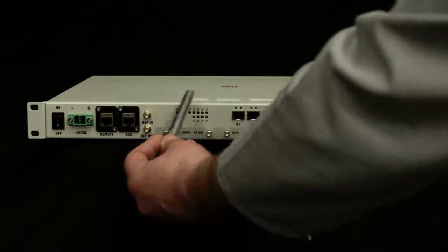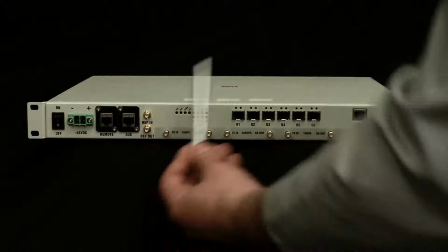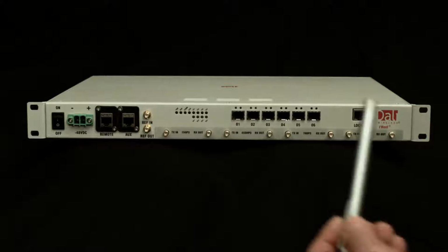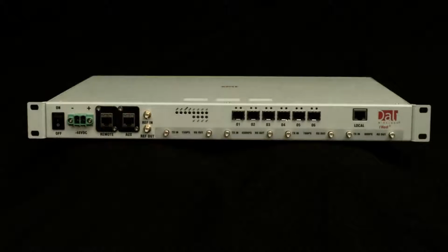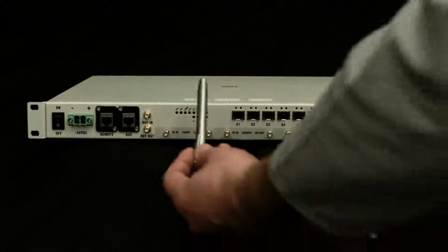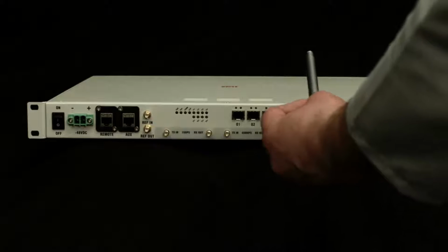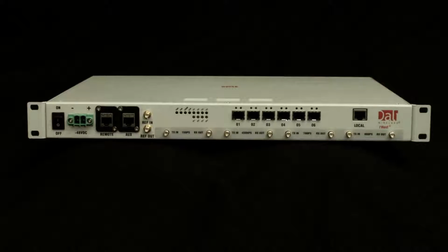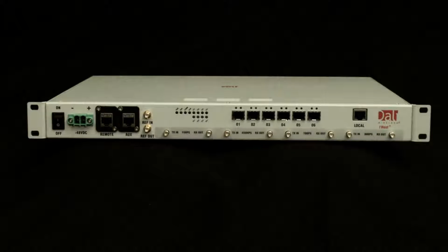Finally, we have a cluster of LEDs on the front panel. Power LED shows the actual applied power. It is green when the power is applied. Run LED shows the health status of the microprocessor. Communication LED shows the actual health status of the link between the host and the remote unit on optical fiber. Alarm LED will go red in the case of a major alarm or orange in the case of a minor alarm.